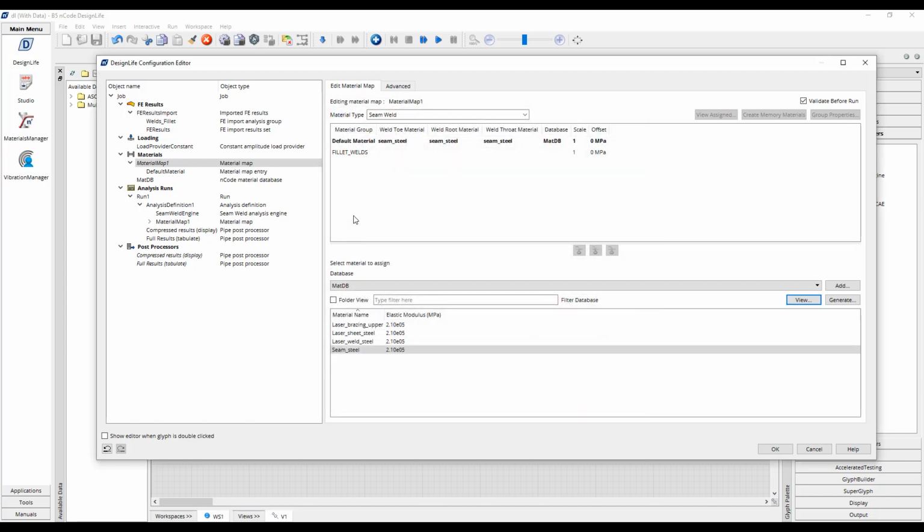All the other material data that's assigned to the other weld bodies, that would be the flange end plates, the vane bodies themselves, they're essentially ignored because only around the fillet welds themselves will the fatigue analysis be conducted.